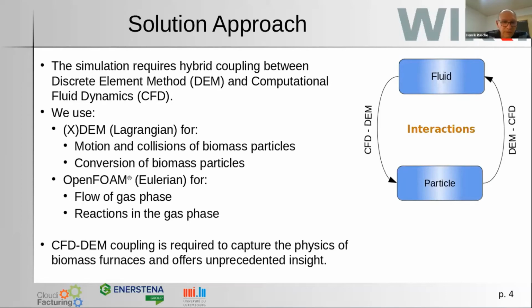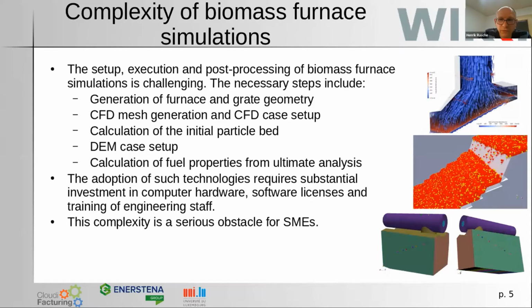So they have very complicated models for the particles themselves. And also they have models for the biomass particles. We couple that to OpenFOAM for the Eulerian phase. So that solves the gas phase and the reactions within the gas phase. And the CFD coupling, it needs to capture the physics and offers quite unprecedented insights into the physics of biomass combustion. Obviously, this is coupled in a two-way manner, feeding data forward and backwards.